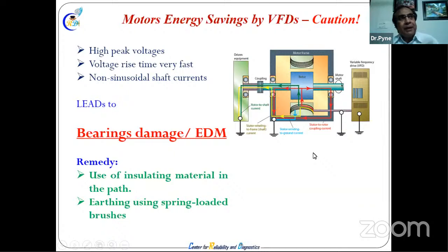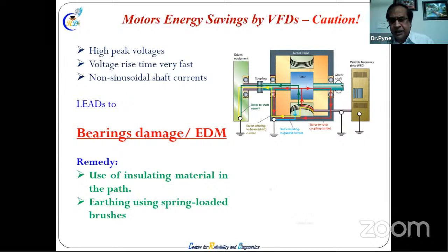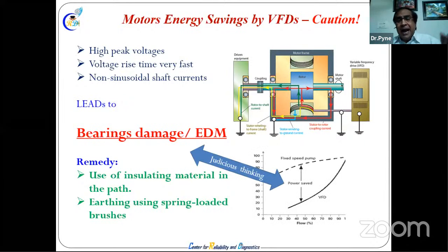So by insulating the bearing or earthing, it should be done. Now if you purchase the latest motor with VFD, question them how well it is insulated. If insulated, what insulating material is taken? Is the casing a separate material, or is the bearing the insulated material? Will it create an interaction, capacitance or other issues or not? Check. You have to check it. So that is the thing. You need to have judicious thinking when putting in a VFD.